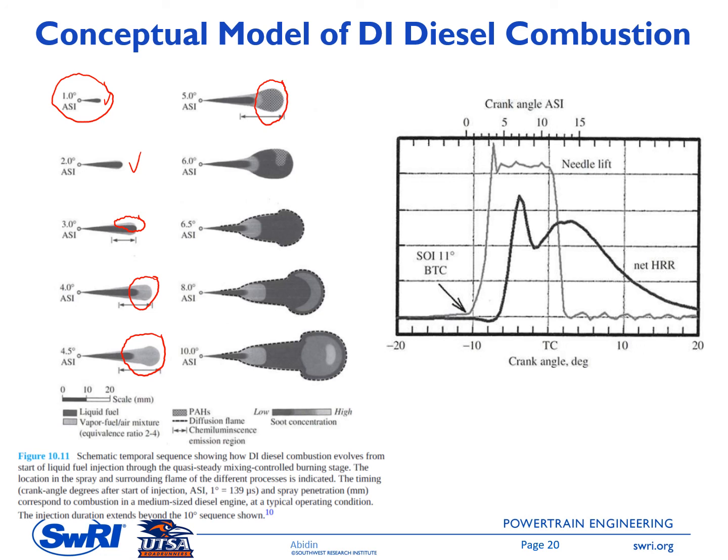This area represents the premix combustion. The fuel has already evaporated, so it's mixed with air, but still at a rich mixture. Lambda here can be between 2 and 4, and then because of high temperature and high pressure, it ignites spontaneously, and